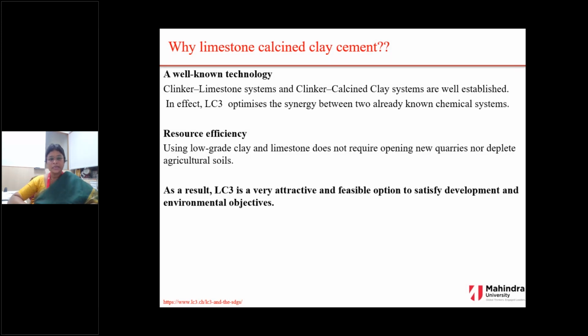The other advantage of using LC3 is that it is a very well-known technology for us. It's not new. The system of calcined clay and limestone used in cement is not anything new. We already know the synergy between the limestone and the calcined clay. The chemical process of adding calcined clays and limestone to cement is well-known and very well established. So LC3 only optimizes the synergy between two already known chemical systems. We already know the chemical system between these two. That synergy is being optimized using the LC3 technology.